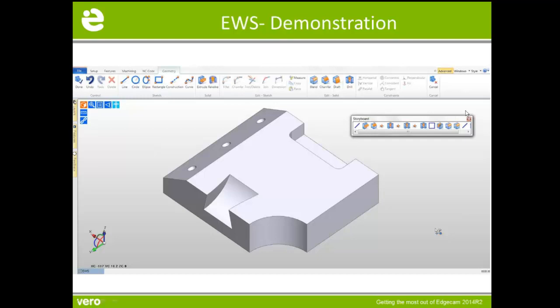Let's just see if we get any more. Can we use it for turned parts? Oh yes, absolutely. You saw me do a revolve command at the end. So a turner would simply draw half a profile, half the step shaft if you imagine it, and then just revolve it. Instead of doing a boss cut extrude, they'd be doing a boss cut revolve or a create revolve.